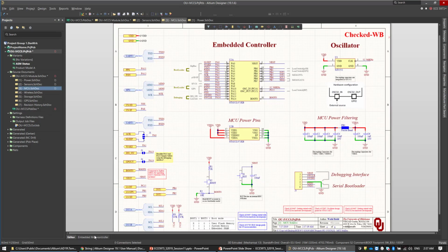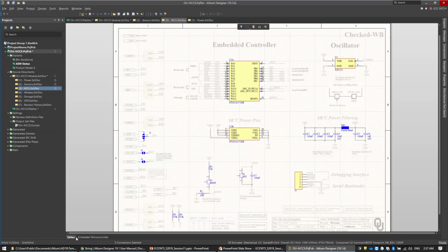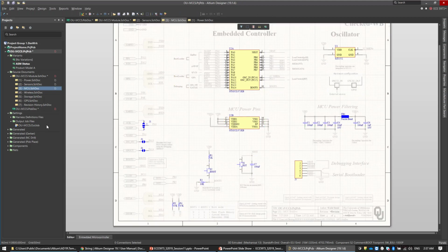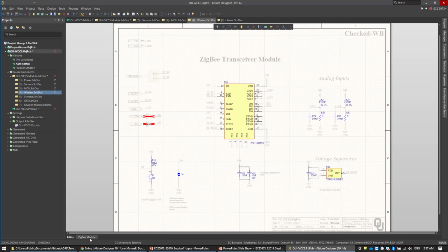Let's take a look. Switch also here down. You have the editor mode and you have the variant mode. All components are assembled. Switch to the variant mode. In the variant mode, you don't see the nets because the focus in here is on the components. The variant configuration is for the components, not for the nets. Here I have two components, or two resistors, that are not fitted.